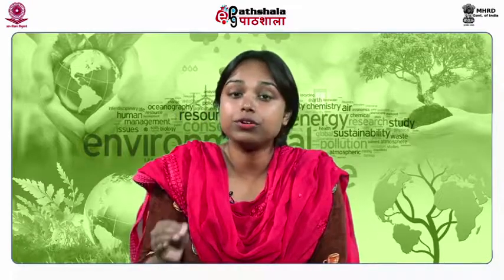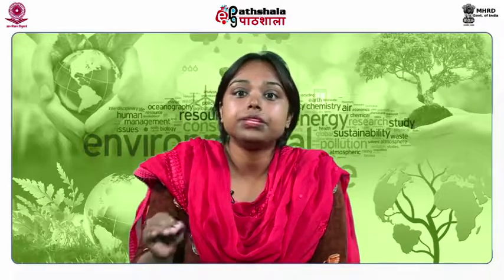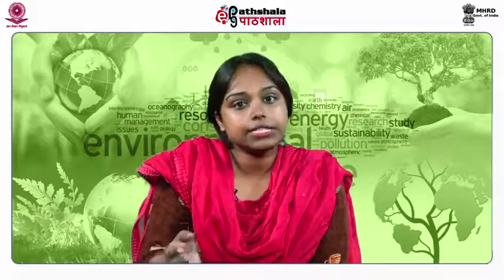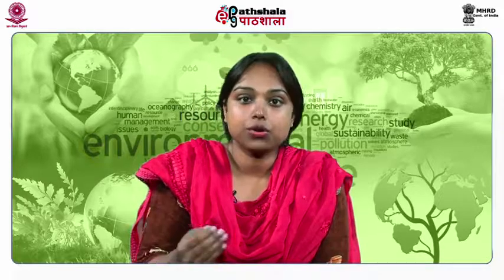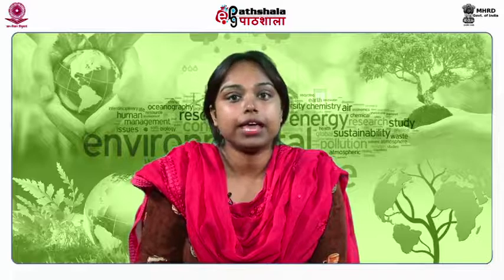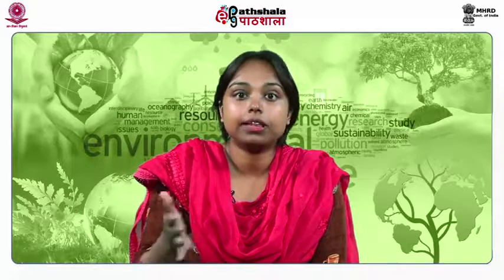Now, to control air pollution, incinerators have to be well equipped with air pollution control devices. The incineration process is conducted at a temperature range of 750 to 1000 degrees Celsius together with steam and electricity generation. At the end, an ash known as incinerator bottom ash (IBA) is produced that should be reused appropriately as it is generally contaminated with heavy metals such as copper, lead, manganese, zinc, etc.